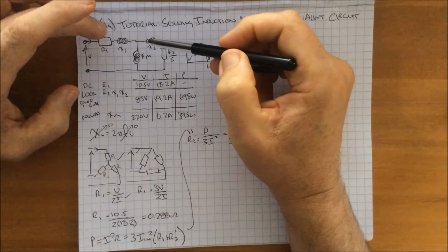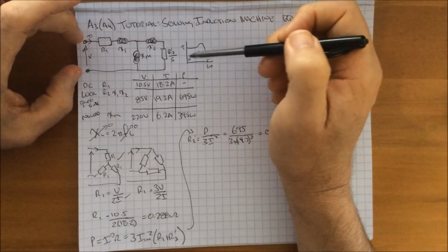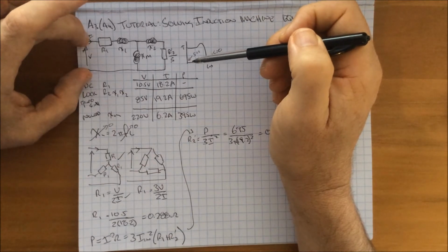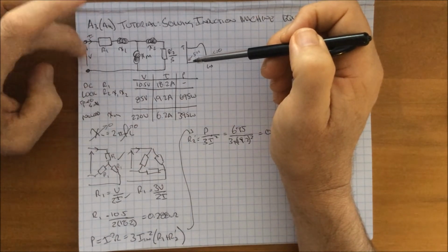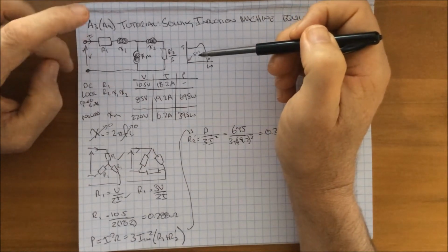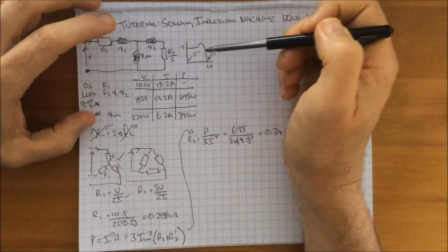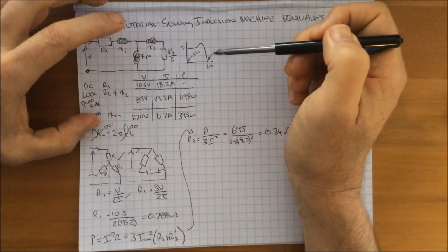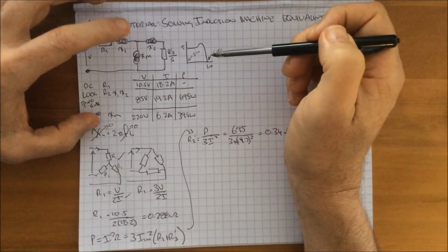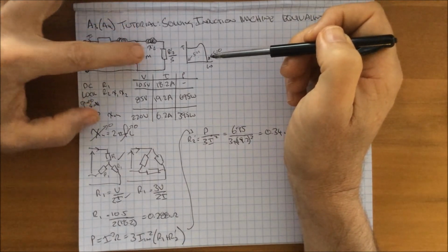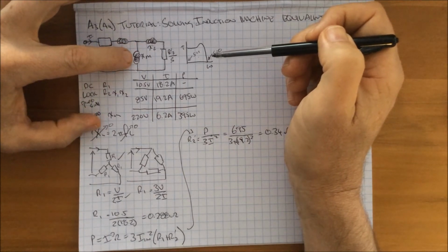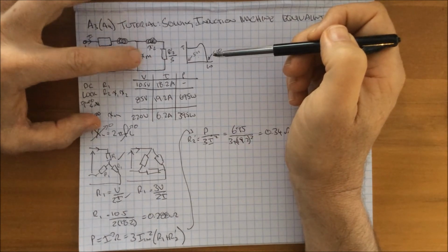We know that the impedance here is voltage and current, Ohm's law. We also, at this point here, are going to make one of the first assumptions that we make when we're building models, and that is that the value here of Xm is high. So we're not going to worry about it.